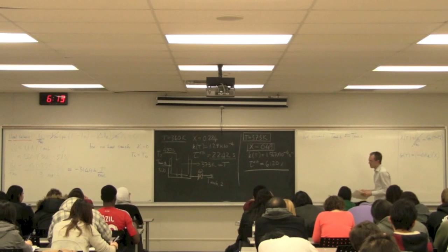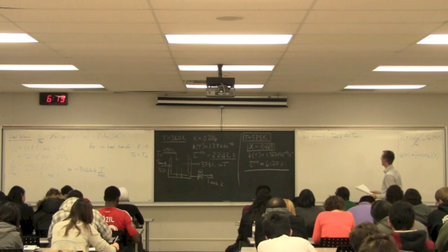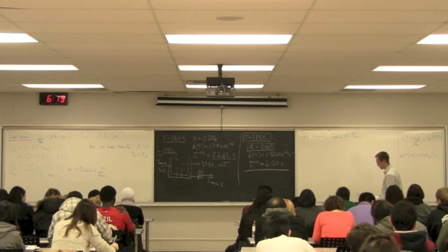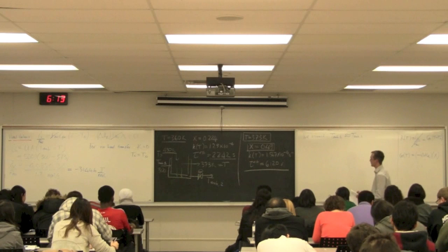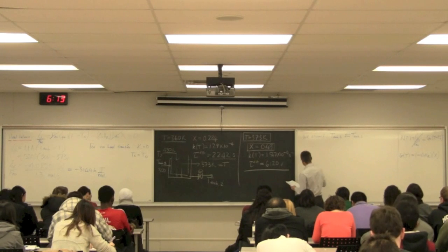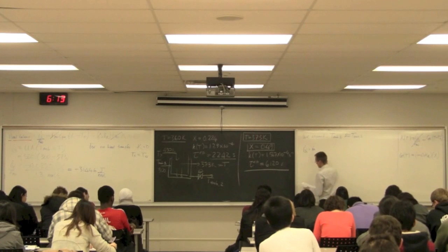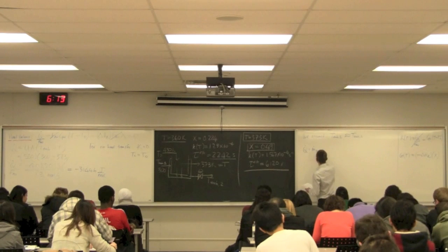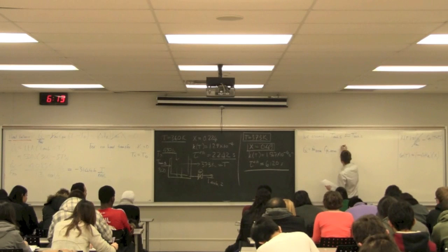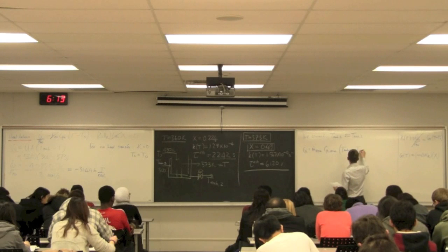Let's go back and look at that assumption and investigate what happens with the numbers. It will also help us estimate what our mass flow needs to be for this coolant. So we come back to the equation that Q dot is M dot, the mass flow of our heat transfer medium, multiplied by the heat capacity of the heat transfer medium, times T ambient 1 minus T ambient 2.